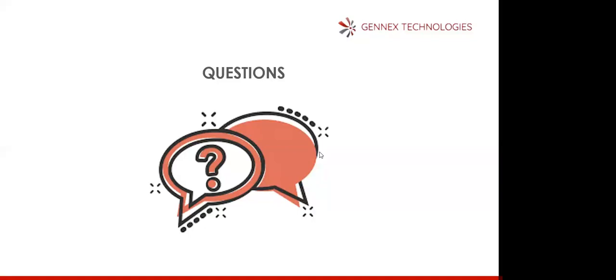Okay, thank you for the question. The appropriate breaker for the input and output breaker for a 5 kVA 48 volt system with 4 batteries and 8 batteries: for the 5 kVA, we recommend a 63 amps breaker for input. Then for the output breaker, we all know that the battery is a backup for the load.